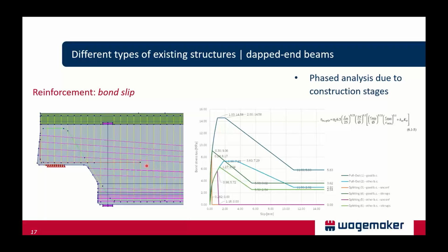So basically, due to the development of shear stress between the bars and the surrounding concrete material, slip develops, which may result in a rather ductile behavior or a rather brittle behavior, and which bond slip relation according to FIP model code should be used depends on parameters such as concrete strength, diameter of the rebar, coverage, and location